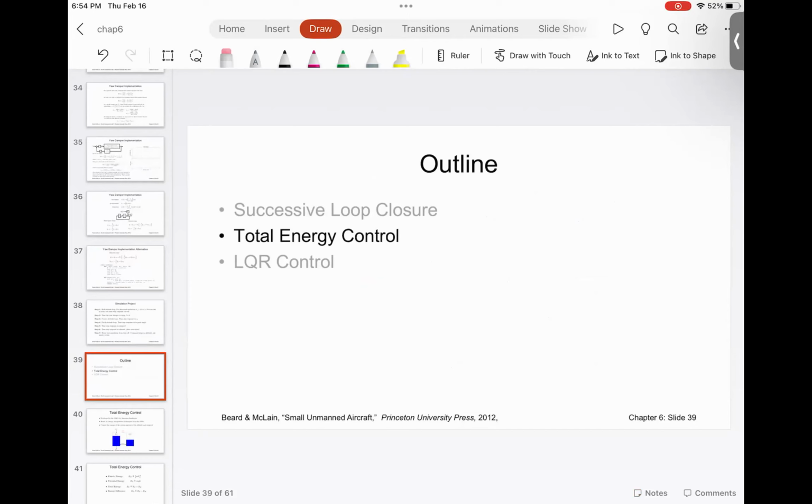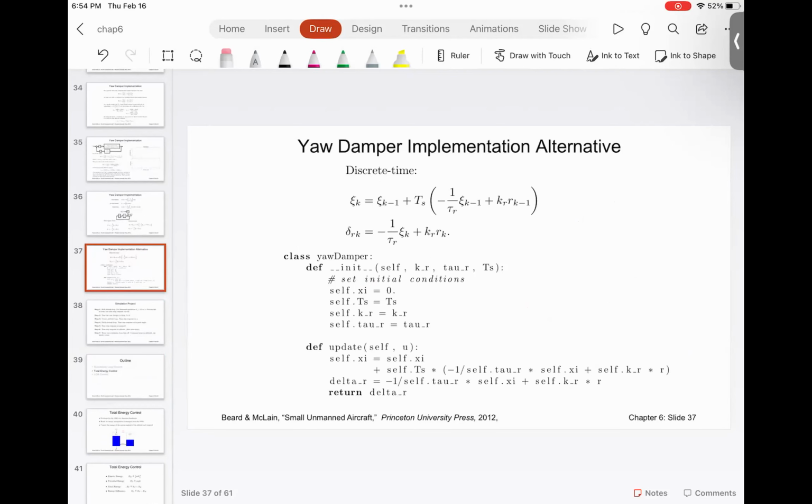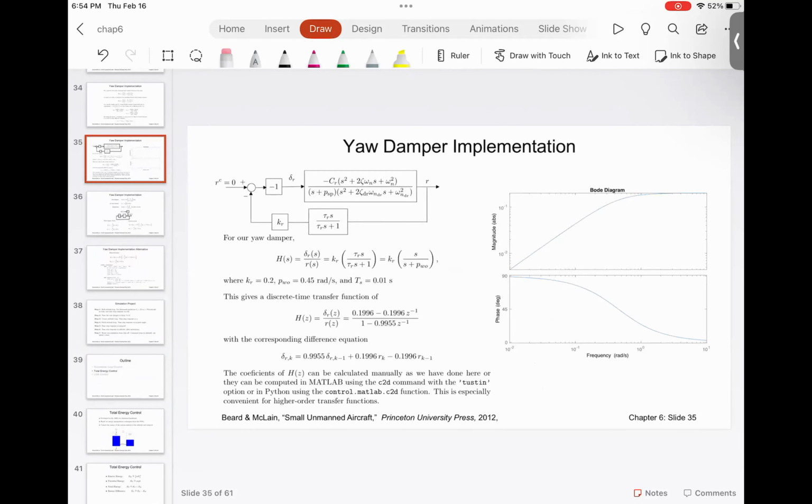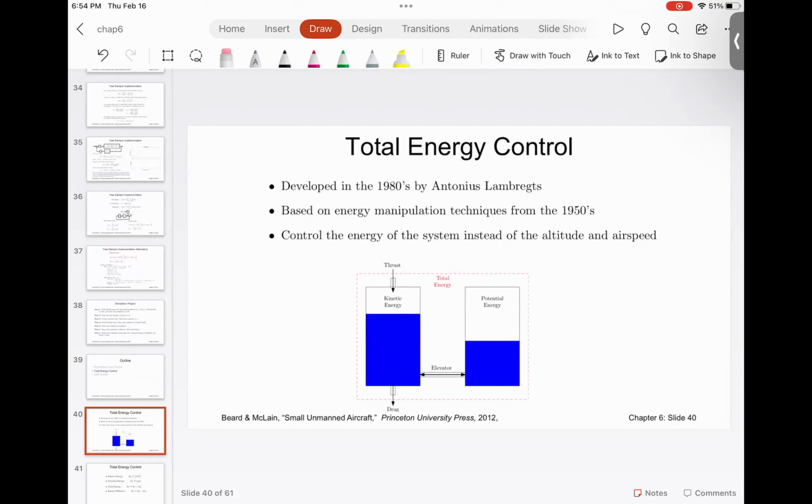Question. When you say the internal loop gain should be one, the intuitive idea is to get a more reactive system: given an input, you should get the actual output. Yeah, basically whatever is the input should become the output. The problem is when you say that y of s upon x of s is equal to 1 and equate that with the transfer function, I'm assuming you add some value to kp and kd. What about the s value over there, when we are dealing with three variables, like kp, kd and s itself?